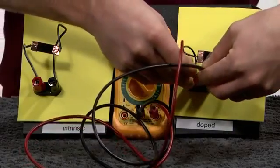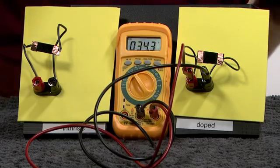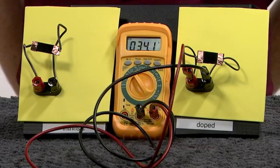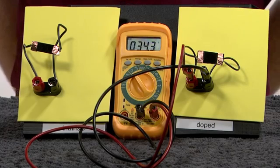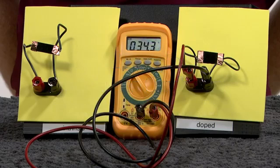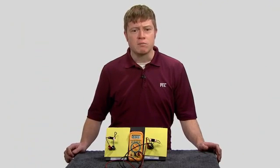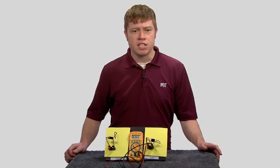Let's compare this to the doped sample. We read a resistance of 34 ohms, which corresponds to roughly 0.6 inverse ohm centimeters. So we can see that the doped sample is around 3,000 times more conductive. But why would adding a small amount of our dopant, about 1 phosphorus atom for every million silicon atoms, make our sample 3,000 times more conductive?